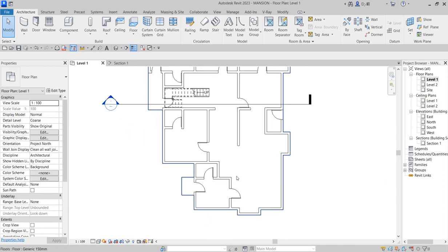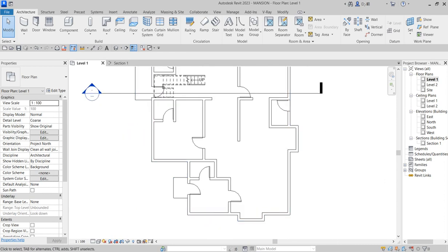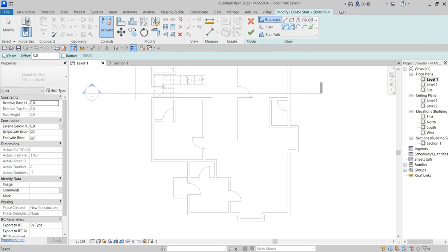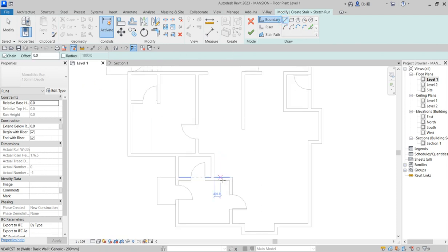Now we want to create the next staircase, which is what? Something like up. And how do we do that? We want to bring it, so we use CSS to do what we want to do first before we finally adjust to what we know best. So you click on stair again, then you say edit, then you work on your boundary first. So from here, how do we do it? I want you to start from this edge.